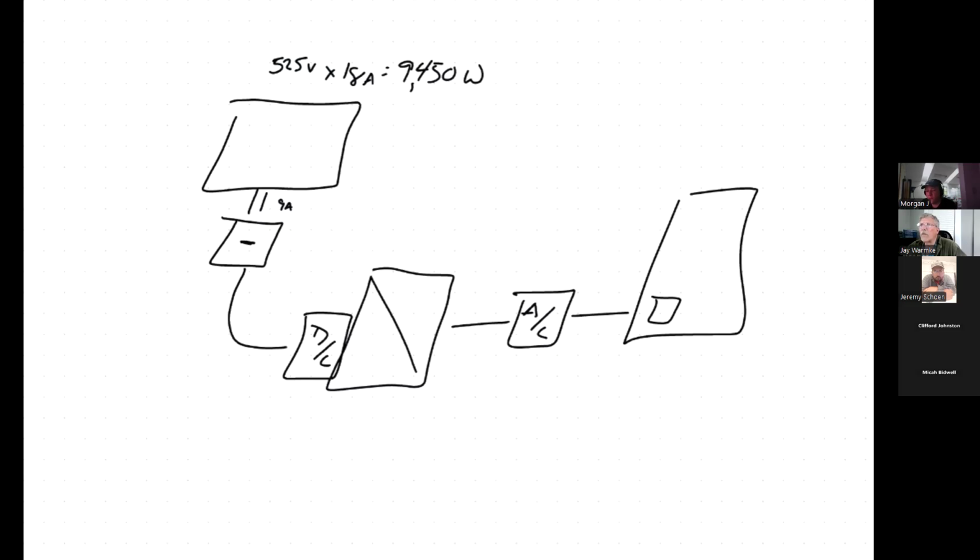All right, so let's size our wire. Well, the wire that goes between the panel and the combiner box already comes pre-attached to your solar panel, and that's going to be 12 gauge wire. Well, we want to look at the table that I've reproduced here in your book. It's page 111. So this is the ampacity table. If we look at page 111, and we know that we're dealing with 12 gauge wire, what's the maximum ampacity that 12 gauge wire is supposed to be able to handle?